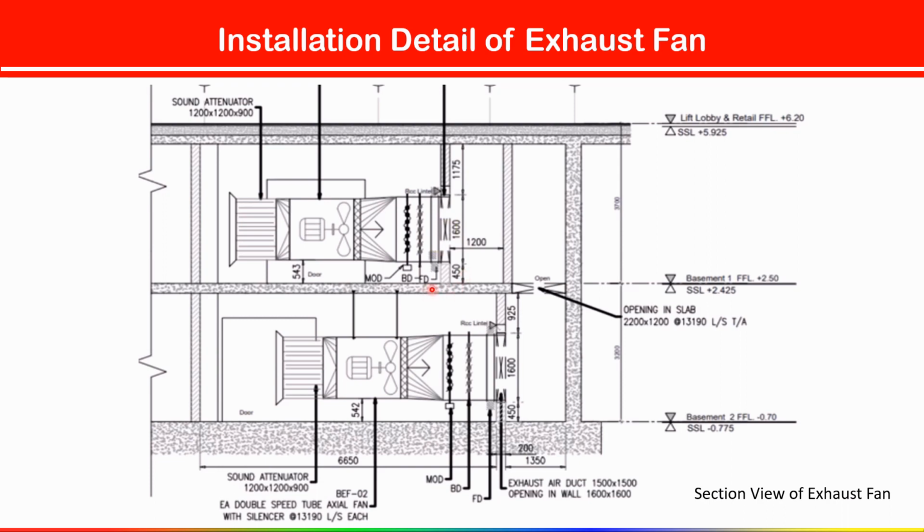That is why we have installed the backdraft damper here. After the backdraft damper, we have installed the FD, fire damper. This damper prevents the spread of fire, which helps to stop a fire from spreading. That is why we have to install the fire damper here. So this is the installation detail of the exhaust fan.